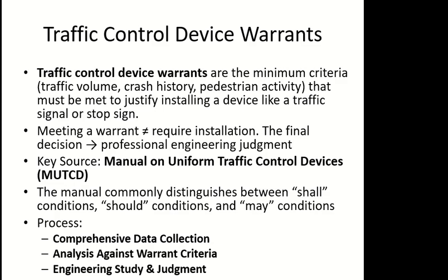Okay, so traffic control devices have some conditions which dictate when they should be used, and these conditions are known as warrants. So what are warrants? The criteria which you follow for using a particular type of traffic control device. If I'm going to use a signal, I will look at the criteria for when to use a signal, and these criteria involve traffic volume. If the volume is this much, we can use a signal. If it is below this much, we should use a stop sign, and so on.